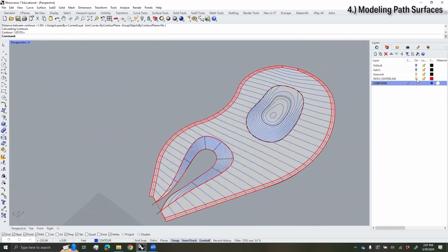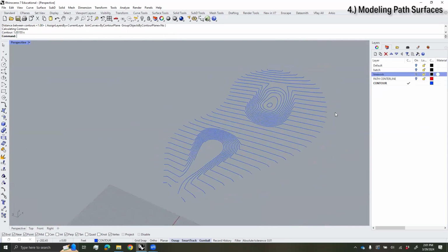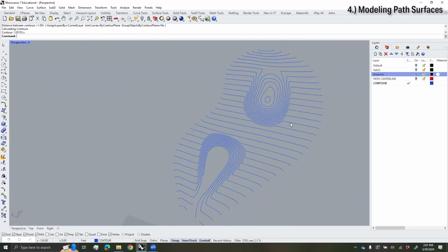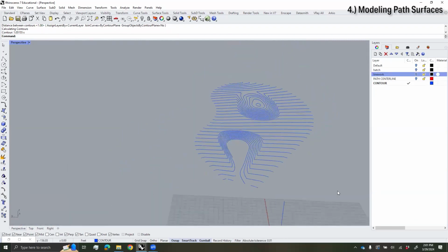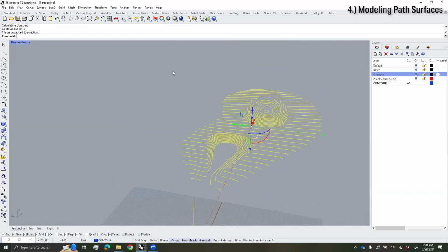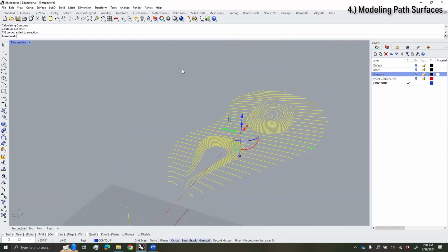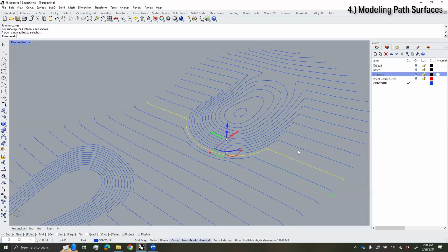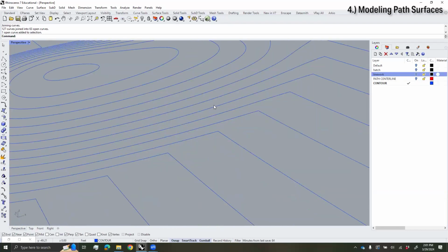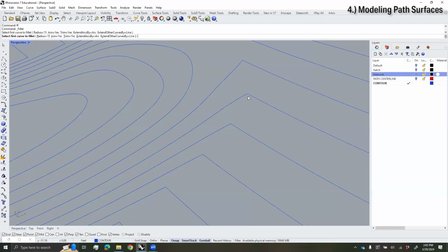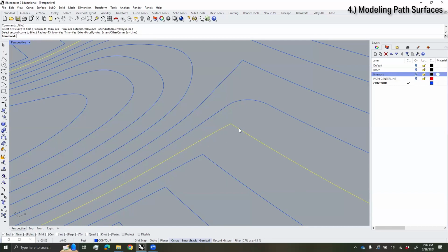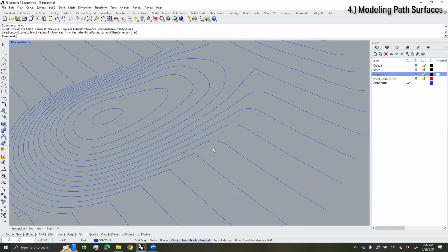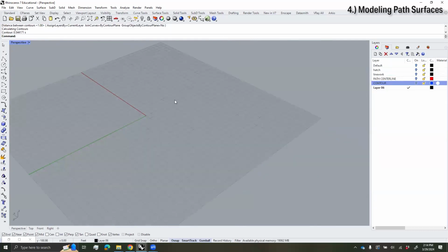And then you have the start of an interesting landform that you can use for your project. And then as you get your contour plan figured out, I would do this to just kind of get things cleaned up. I would join all your lines together and then try to fillet the corners of contours as much as possible. Choose the ones that you want to fillet to kind of create a more organic form and shape to your design. There are a few really simple modeling tools that everyone should just have in their toolkit.